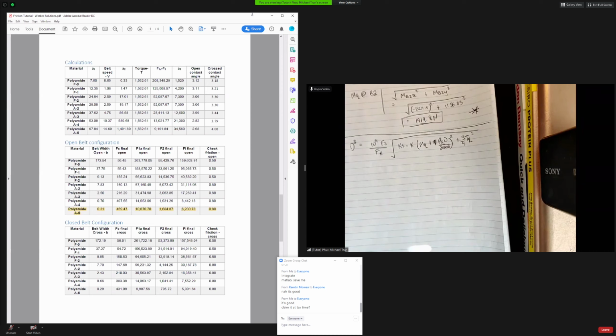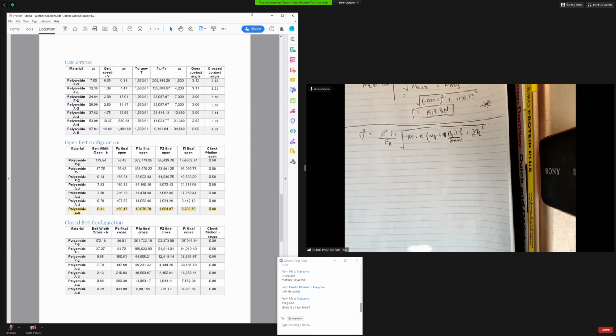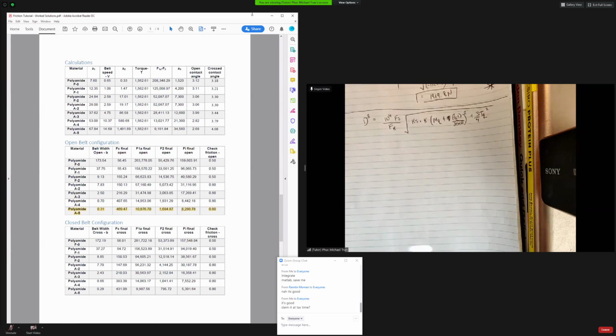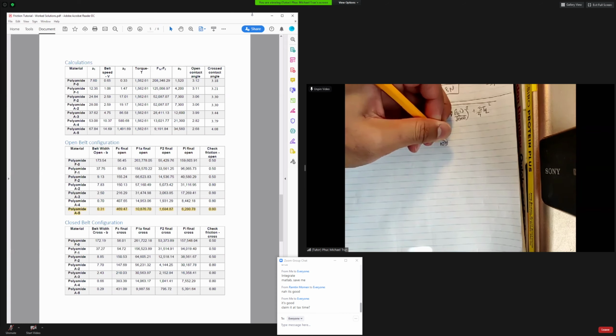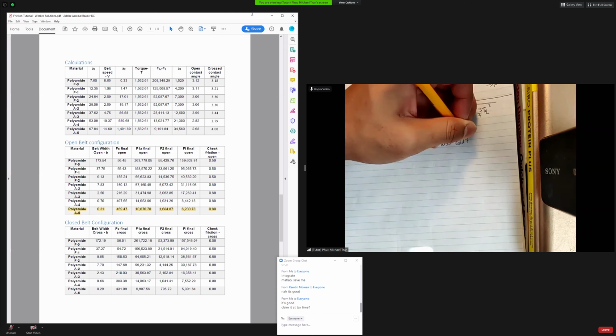All right, what do we have? For FS, it's going to be 1.2 because that's the standard we've been using for the tutorials, so that's constant. For FR, we're going to use the same material as the JDR report, which is a 1030 cold rolled steel.